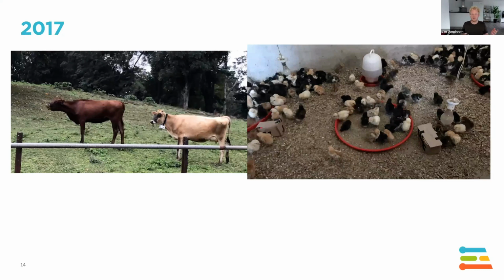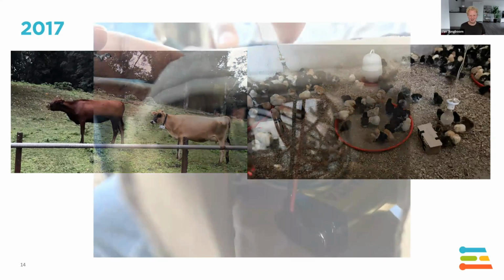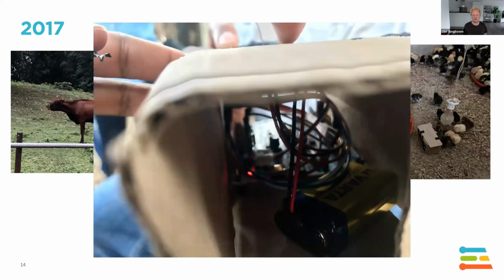This is the interesting part for me, where I started thinking that a couple of dollars is really expensive for a farmer in this case. So we started looking at that, hacking together a system that could generate a heat map from data. The cardboard boxes that you see, one on the right side of the red ring and one on the left side of the picture, were our gobbled-together sensors, and they literally looked like this. This is a Nucleo board, a bunch of wires with some temperature sensors, a little Wi-Fi module, an ESP8266, and a 9-volt battery. Then we put it in a cardboard box, and that was it.